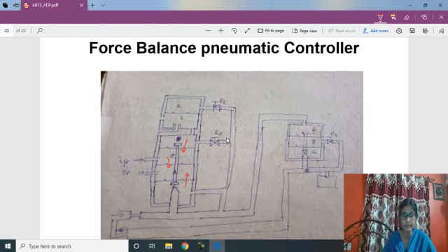So again the pilot valve will move towards this direction, and after a certain time delay, the pressure at chamber A will rise. When the pressure at this chamber rises, the diaphragm between A and B will move downward.